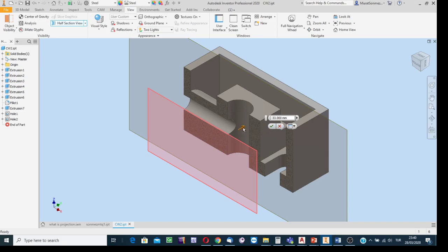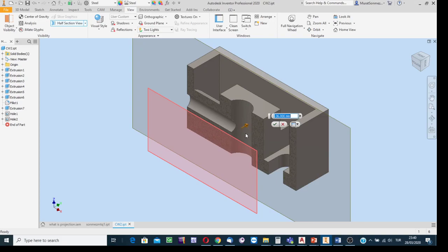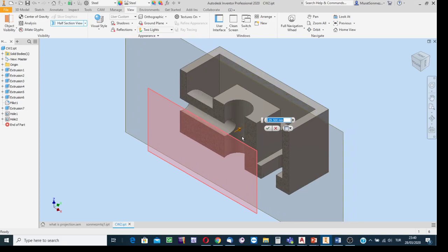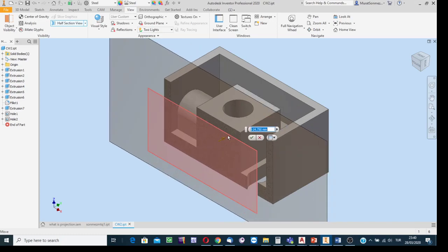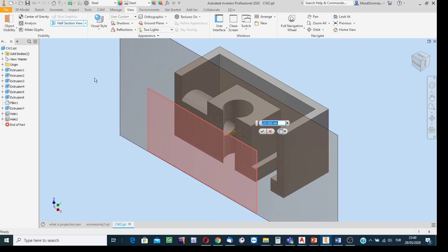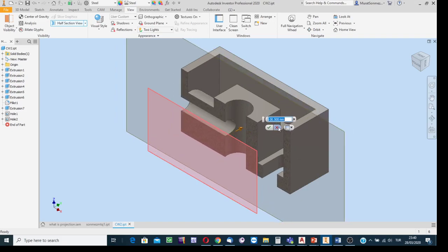But say this is for animation purpose, just demo purpose. This cross section, that is the geometry. This cross section here is the geometry. That cross section, that is the geometry. To be able to use the sectional view creation tool of Inventor, well, this animation is not needed. This is just the tool to demonstrate the sectioning process, to decide which cross section is the most suitable cross section for outputting a certain sectional view.